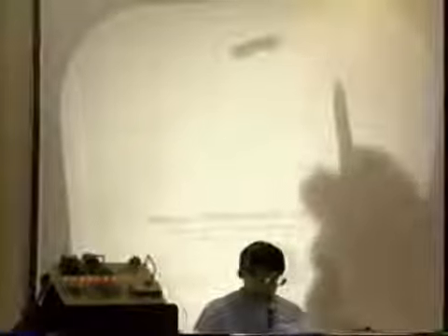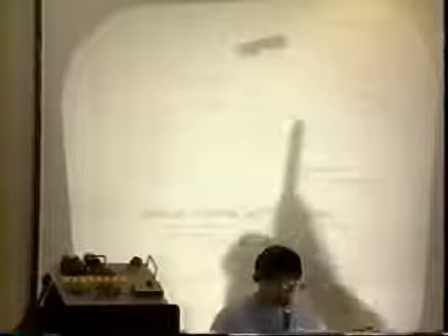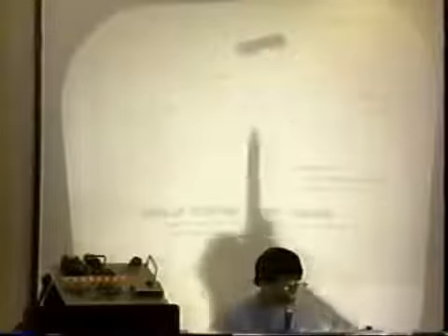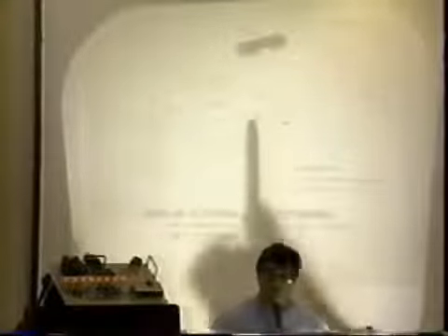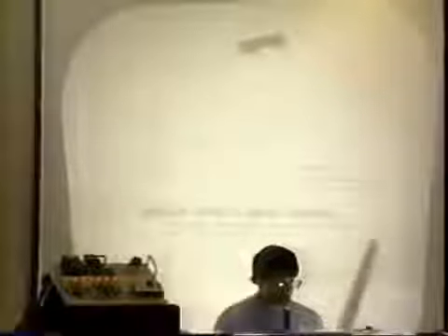Most people do not publish circuits for this because the circuit requires that you use bipolar circuitry, and people don't realize you can get that whole thing on one little chip. All I'm doing here is sending out the binary numbers 0123, 0123, 0123, and this thing goes through its 4 combinations automatically from this chip. And since I'm only using 2 bits, I could add 3 more of these things, and I could have 3 more stepping motors. I can run 4 stepping motors from one parallel printer port very, very safely.